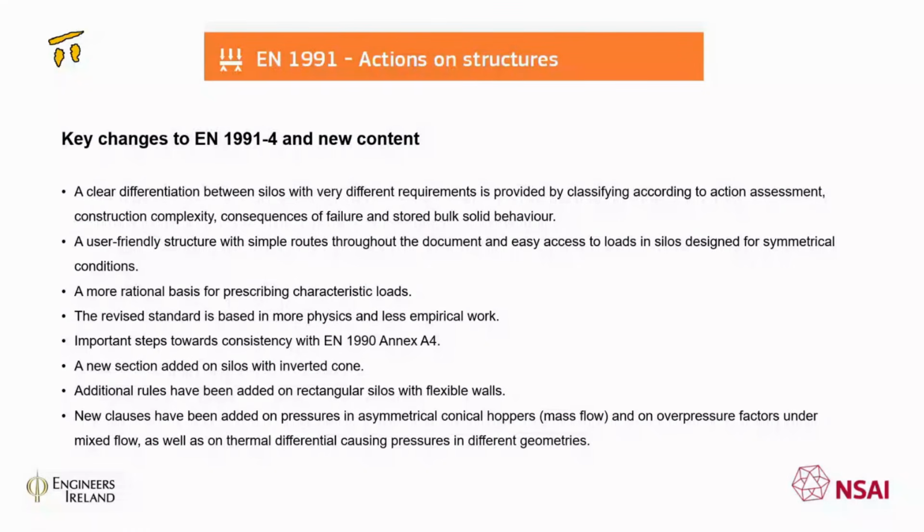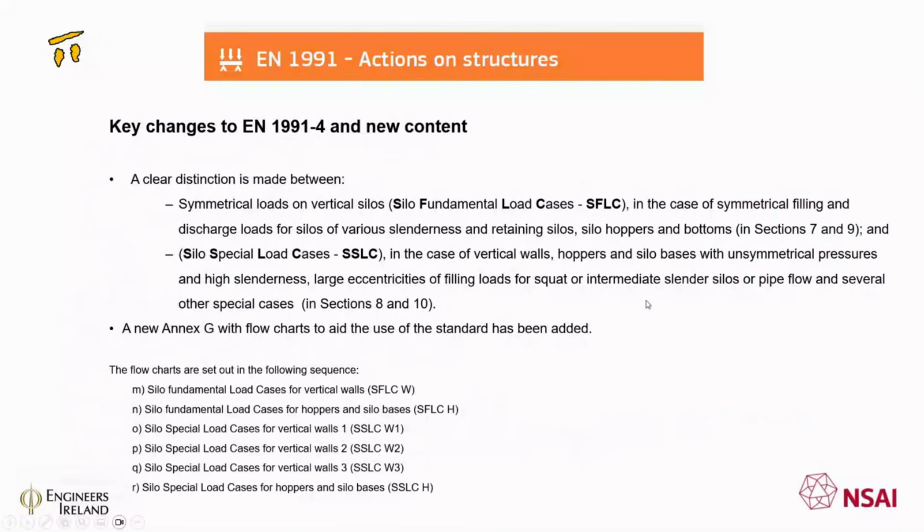Finally, I think this is the last slide. There's a clear distinction made between symmetrical loads and vertical silos and special cases where there's unsymmetrical pressures and high slenderness, large eccentricities, etc. So there's a new annex given to set out how that has been used, and that is given in a series of flow charts.